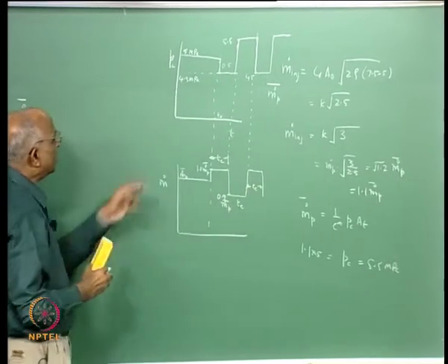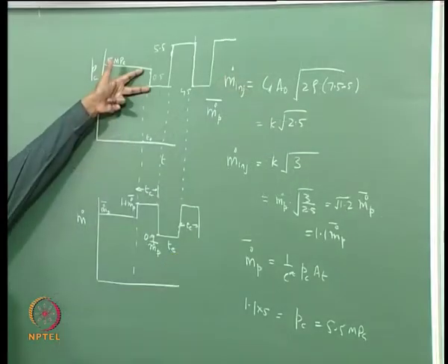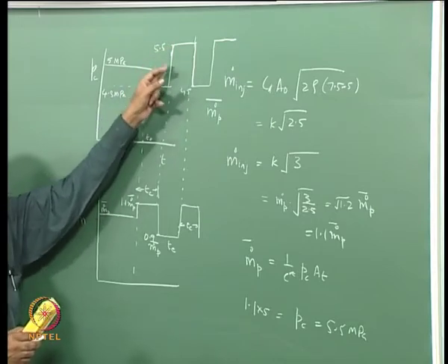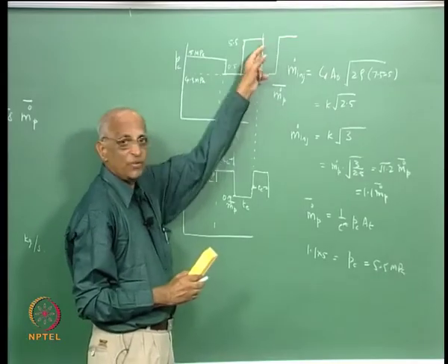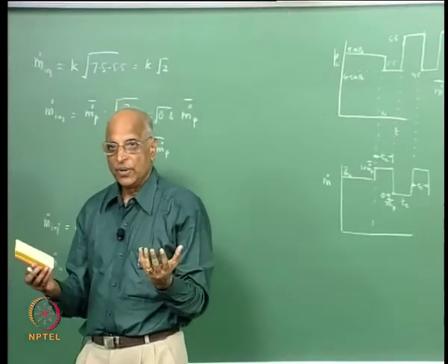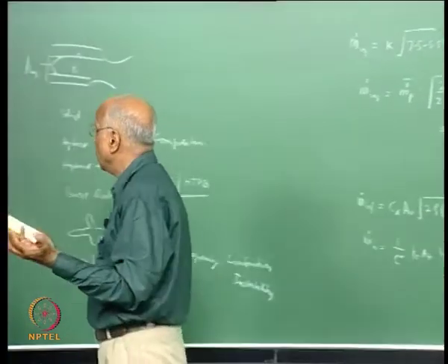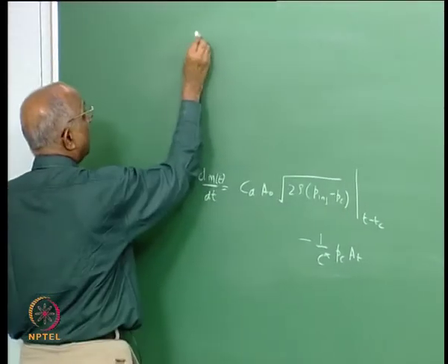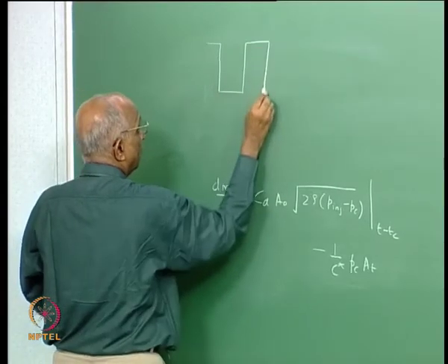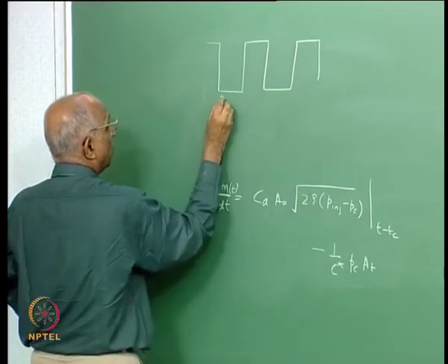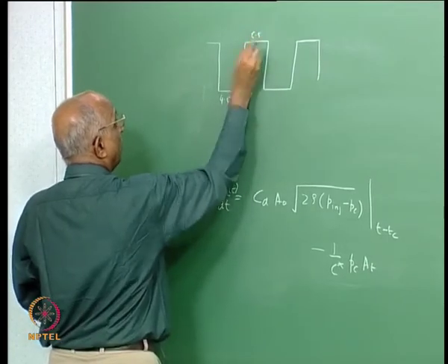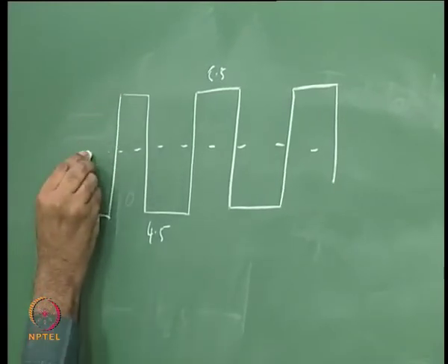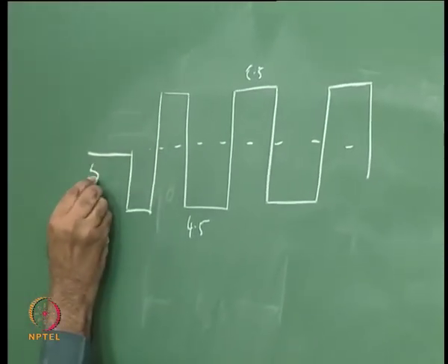You find that a momentary drop of 0.5 makes the chamber pressure oscillate between 4.5 and 5.5, to 4.5, to 5.5. Out of a steady situation, when you have this delay term, you started getting oscillations. The oscillations are neutral, in that it keeps fluctuating between 4.5 and 5.5, whereas the nominal value before the drop was 5 MPa.